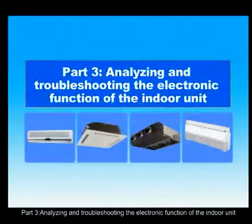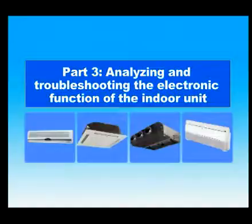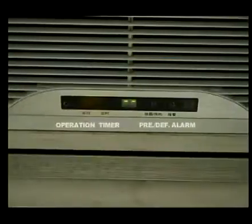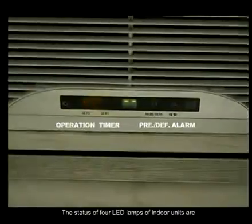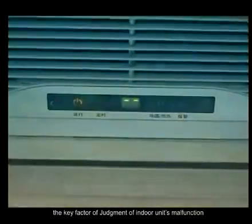Part 3. Analyzing and troubleshooting the electronic function of the indoor unit. The status of the 4 LED lamps of indoor units is the key factor in judging indoor unit malfunction.